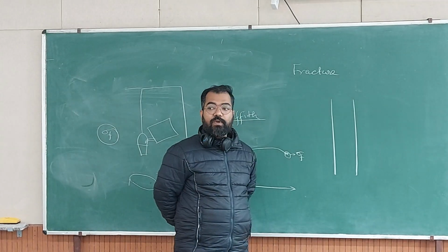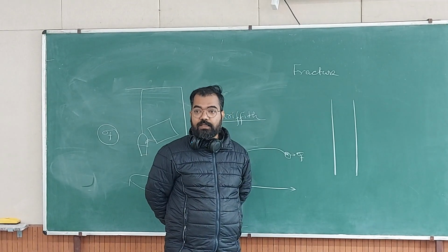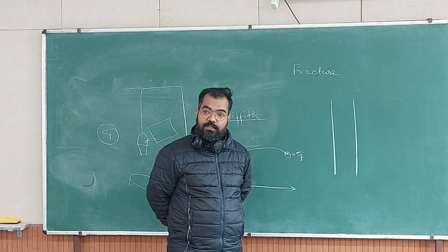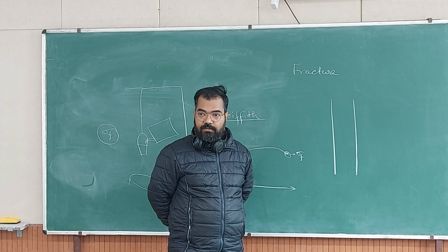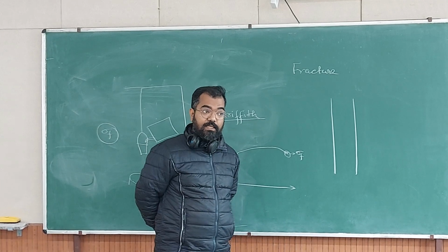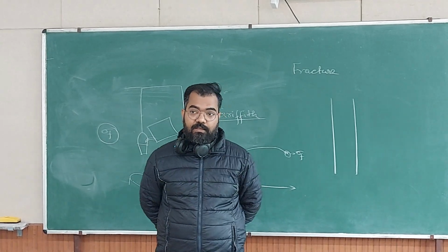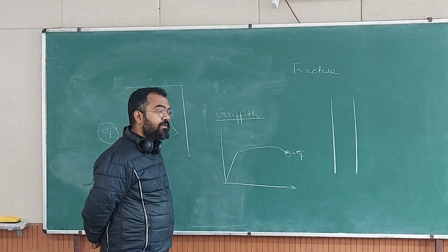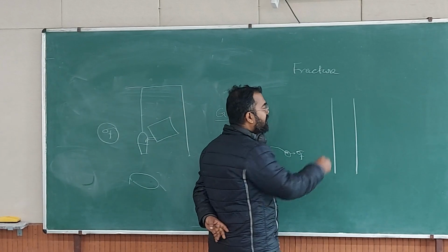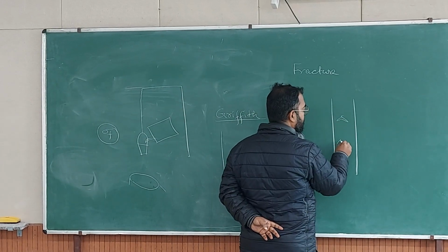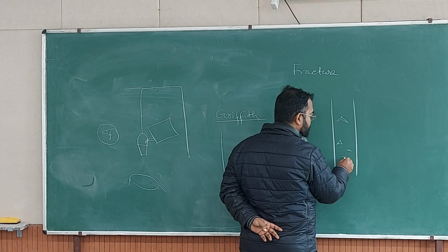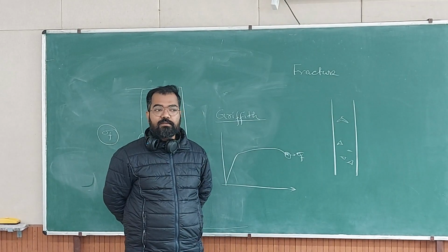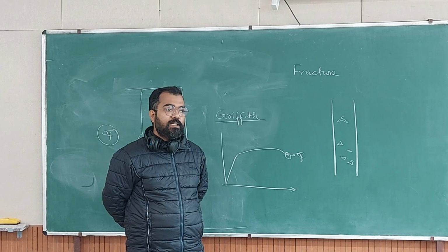So when you have carbide or graphite, in which form are they? They are in the form of flakes unless you make it a spheroidal cast iron, or globular cast iron, where carbides are in a spherical shape. If you don't do that, even if they are spherical, that is okay. The same phenomenon will happen. But you have flakes of carbide, not of this size, but something like this. So now tell me where the necking will happen, if at all it happens.